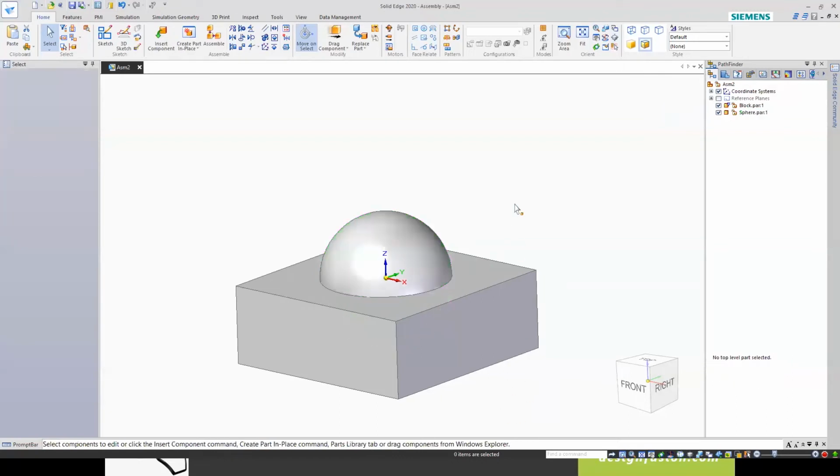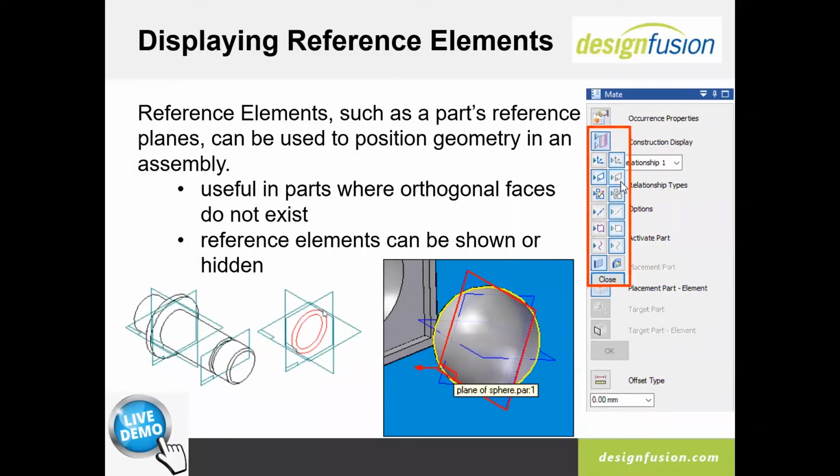Now, this is quite useful when you get a complex or challenging positioning scenario. For example, I have this O-ring and I want to center it in this slot. I can actually position a plane at the center point using a global plane in the assembly. And if I've drawn this centered around 0, 0, I can then turn these on and align this plane with this plane, and that perfectly centers it inside of a slot. This is the type of example where it's quite useful.